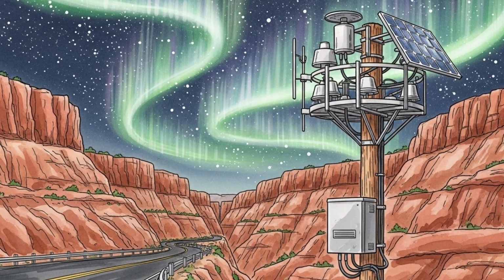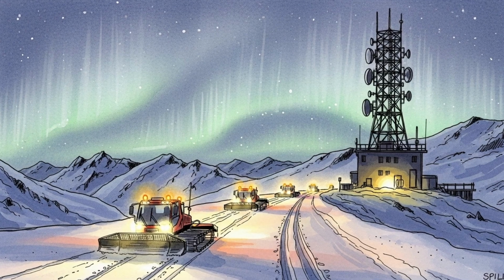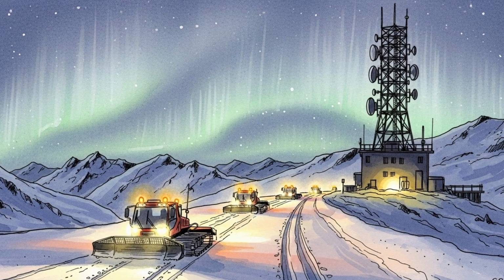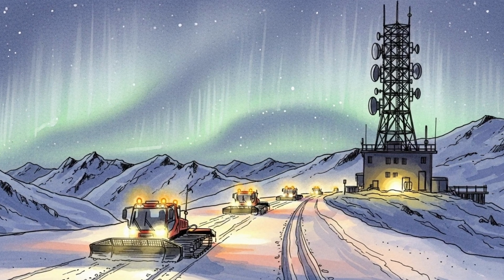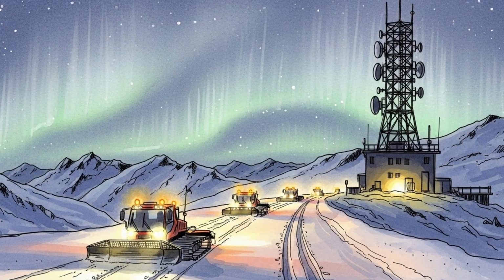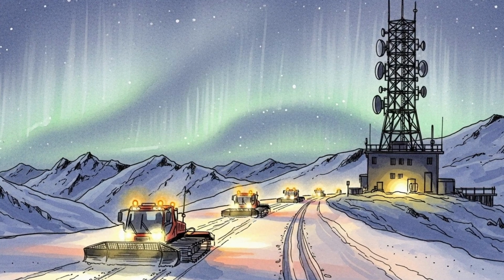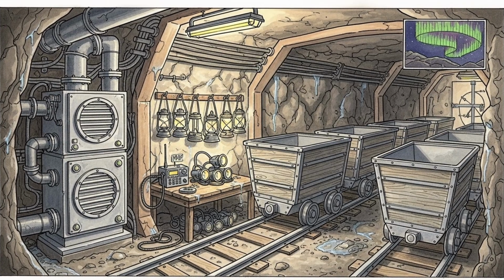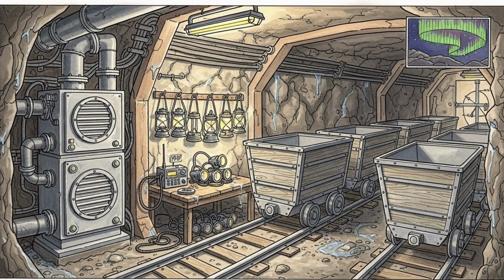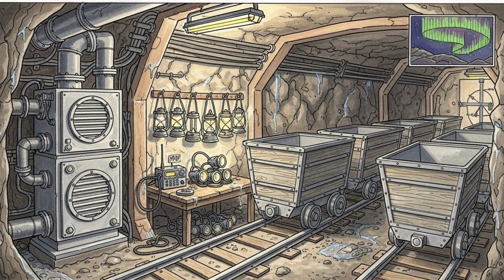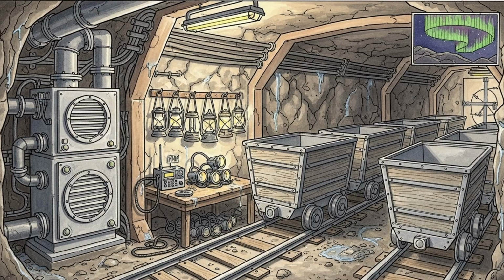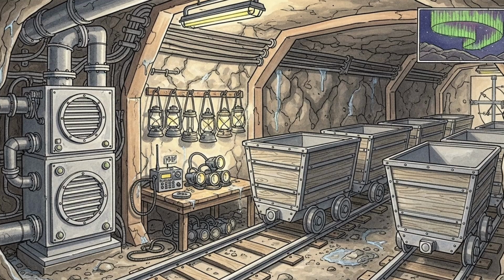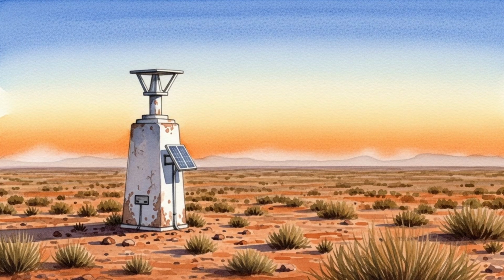Reinforced scenario with localized equipment damage. Coupling remains strong for many hours. dB/dt peaks several times. In power systems, multiple large transformers enter partial saturation. Reactive demand rises and stays high. 1 or 2 units overheat and trip. Protection blocks or bypasses some series compensation. A regional island separates to protect stability. Load shedding is applied in blocks to hold voltage. Restoration requires several hours.